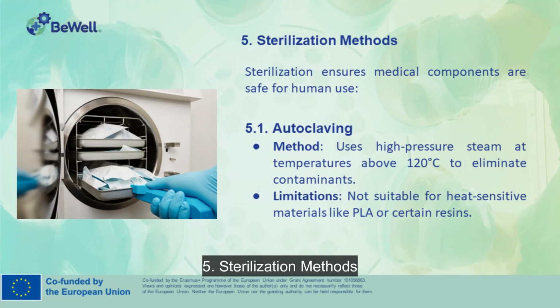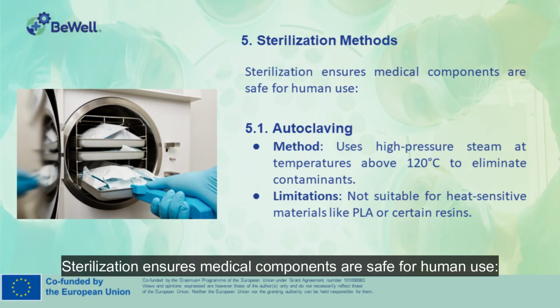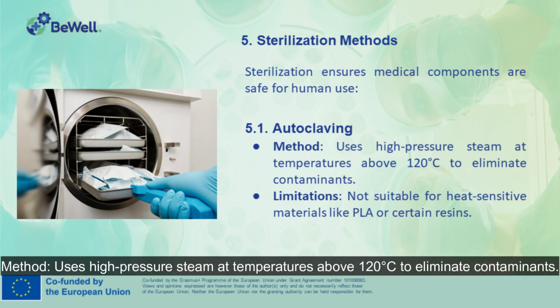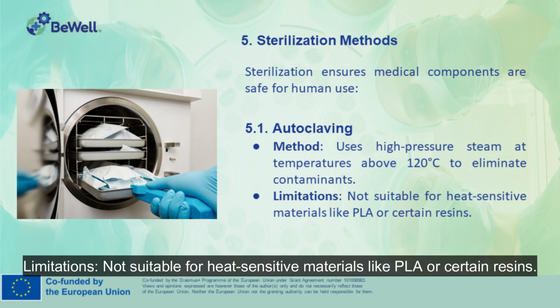5. Sterilization methods. Sterilization ensures medical components are safe for human use. Autoclaving. Method, uses high-pressure steam at temperatures above 120 degrees Celsius to eliminate contaminants. Limitations, not suitable for heat-sensitive materials like PLA or certain resins.